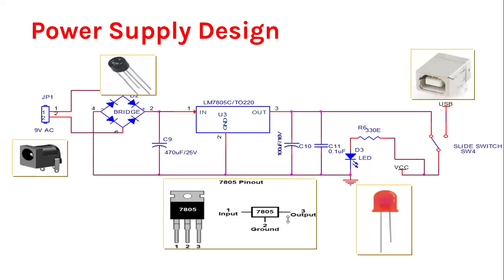Remember one thing, guys: the IO capability of the microcontroller is only 5 volts, you mentioned 9 volts. 3.5K? There is no guessing, guys. You must find the exact value.